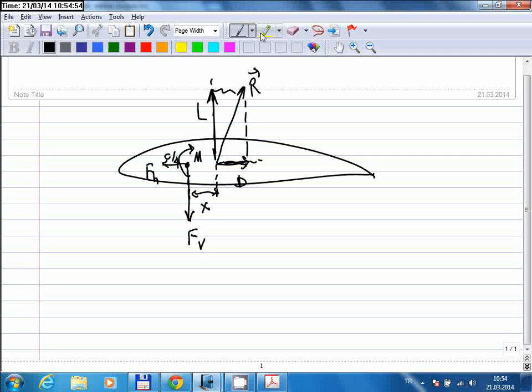Okay, so let this be the wing in the tunnel. I'm holding it from here. If I turn the tunnel on, some aerodynamic forces develop on the wing, right? And if I try to hold this steady, I should apply a larger force with my hand. Otherwise, these forces will try to move it. So as aerodynamic forces develop on the wing, the same forces in the opposite direction should be applied at this point where it is held steady. And the total force should be zero since it doesn't move.